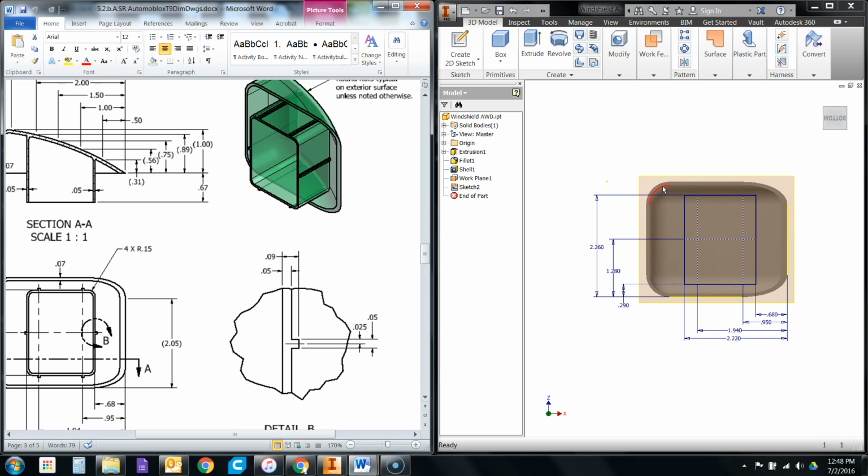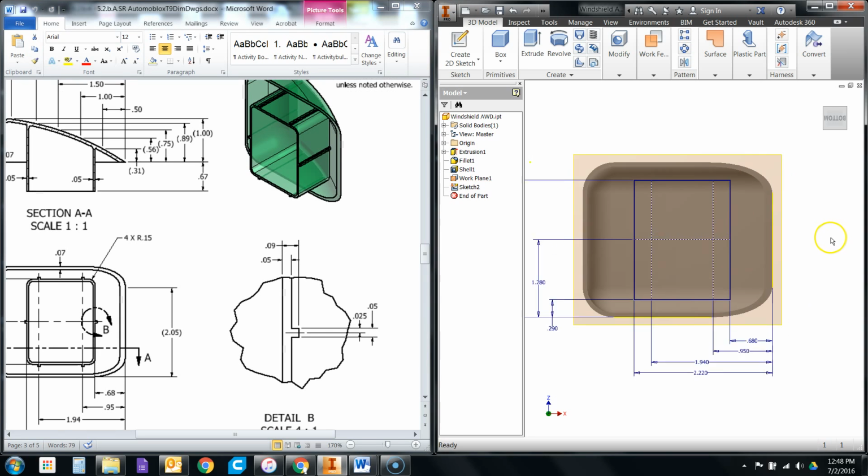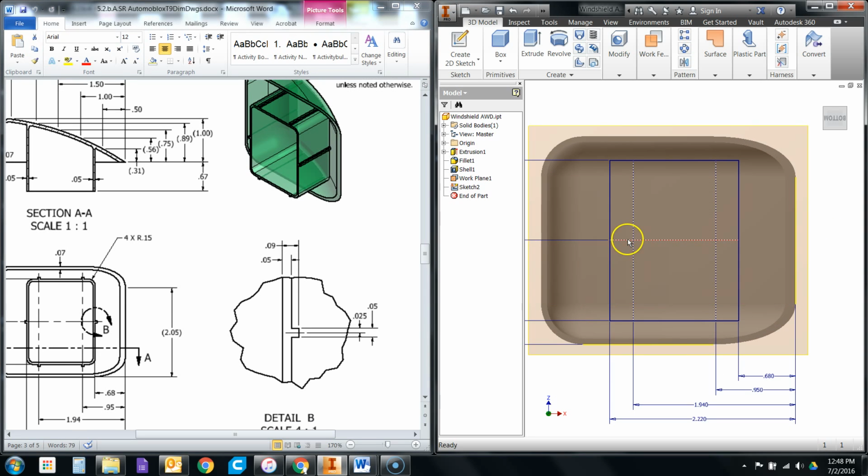Now, I'm going to go ahead and draw them in this sketch. I'm then going to extrude the rectangle once I've filleted for these corner edges so that it goes all the way up. I'll shell it, and then I'll share this sketch, and I'll take those little rectangles that I've created and extrude them as a separate extrusion. That way they don't shell with the rest of it. If that's confusing, it's okay. I think you'll see what I'm doing as we move along.